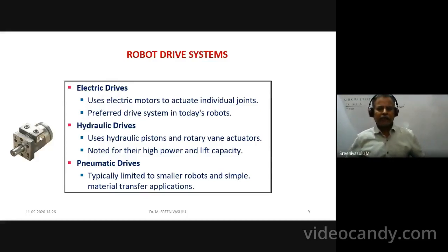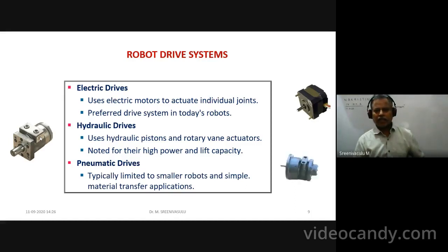Once we have some kind of leakage, that causes a failure for our system, because you are trying to give an input to do something, but because of the leakages present at the seals or at the joints, whatever pressure you wanted to transmit, with which you wanted to make the actuator function, it will not. Same is the story with pneumatics. Even over there, you are going to have similar devices. You can see those images, similar to what you have for hydraulic.